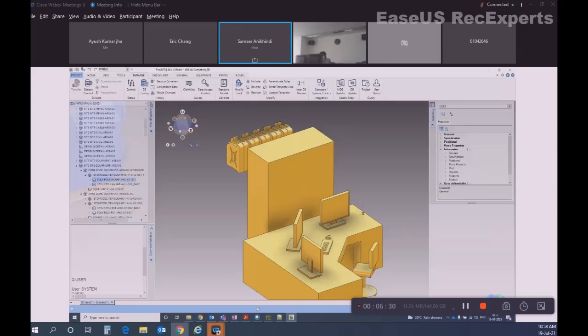To activate or deactivate snap, you can use this key. Deactivate means no snapping will be visible. If I bring somewhere near here, it will not snap. Or the shortcut key, just like AutoCAD, is F3. You can see F3 activates the snap. F3 again deactivates the snap. Sometimes you are working in a very dense, complex area, and you do not want to mispick anything. That's how you can use F3 to turn the snap on and off.